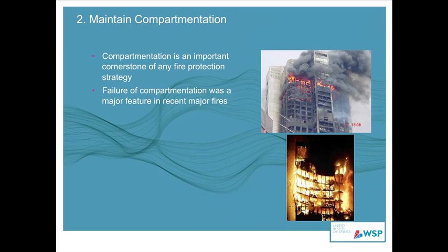The columns were totally unprotected on the outside of the building. There were major breaches to compartmentation internally, because there was no fire stop, and in fact that was part of what was being refurbished. So this building is probably not a good example of a modern designed building in service. It's actually a good example of what happens when a lot of that protection is taken away.